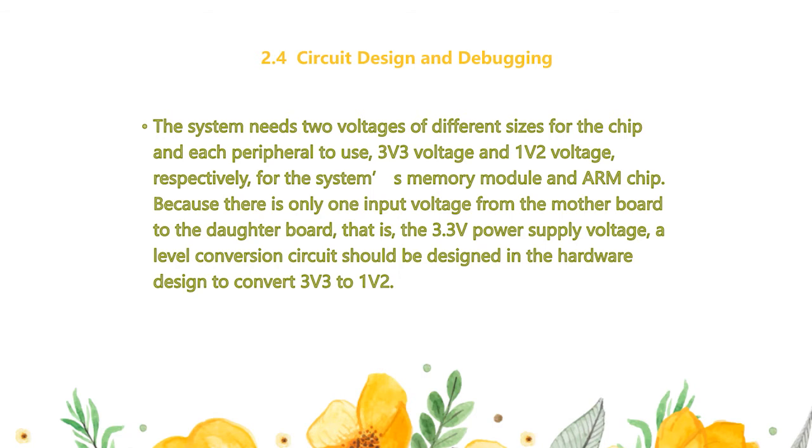A level conversion circuit should be designed in the hardware design to convert 3V3 to 1V2. In addition, the crystal oscillator circuit is an indispensable part of the embedded hardware circuit, and the ARM chip obtains the master clock by using an extra crystal oscillator for frequency multiplication.